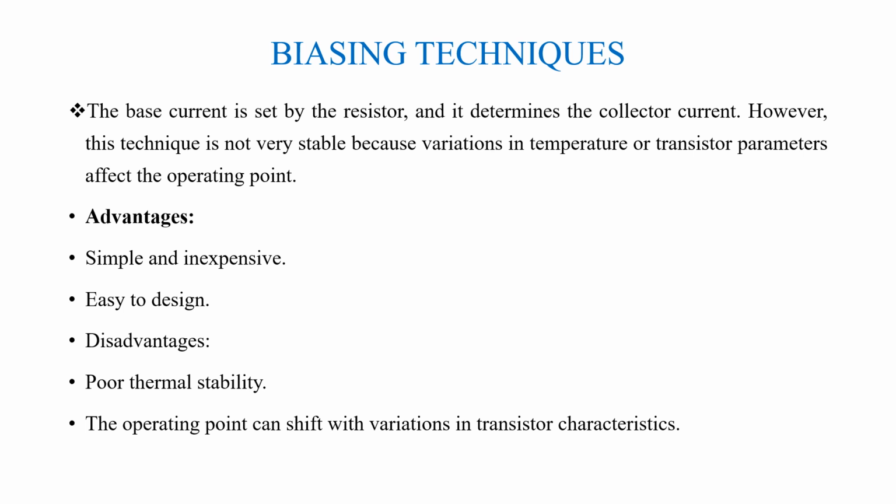But this technique is not very stable, and there can be variations in the operating point due to temperature or transistor's parameters. Advantages: simple and inexpensive, easy to design. Disadvantages: poor thermal stability. The operating point can shift with variation in transistor characteristics or temperature variations.